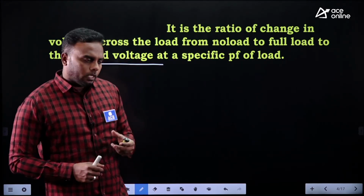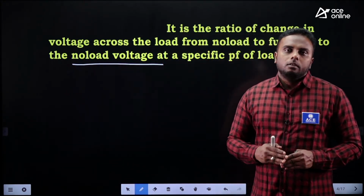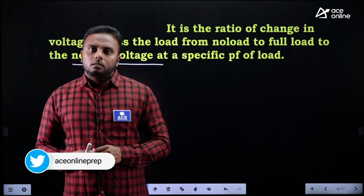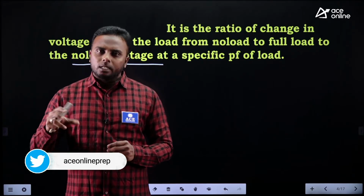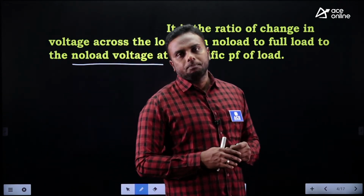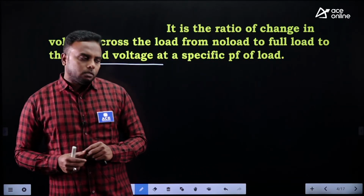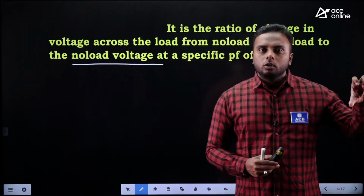For that, in most of the transformers in substations, we have tap changers. Based on the percentage regulation at a particular load, we have some percentage of tap changing: 4% tapping, 5% tapping, 2% tapping, tap up, tap down we call. Tap up we do generally for lagging power factor and tap down for leading power factors, because whenever loads are leading, capacitive loads, receiving end voltages will increase.